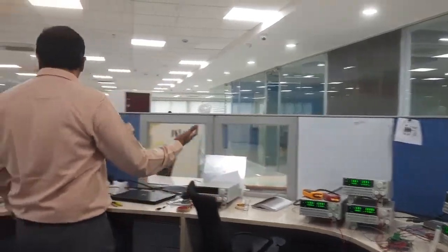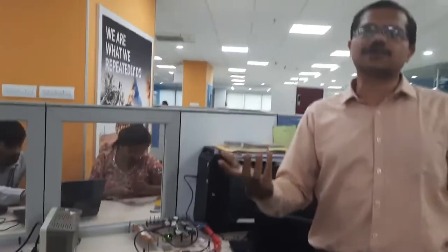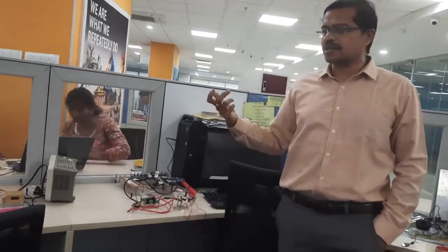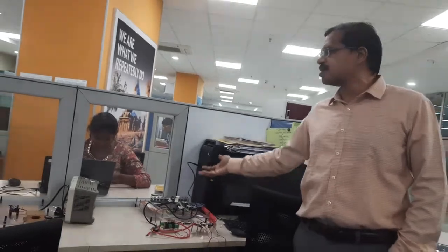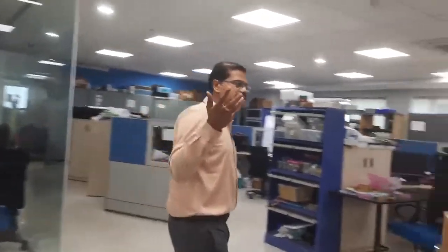After the power supplies, I am showing you some circuits related to level translators. When you are distributing from FPGAs to microcontrollers to i7, i3 computers and all, you require level translation to be done. Here the testing is going on for some of the level translator circuits. At Unistring we use these kinds of power supply systems and control circuitry, built sometimes with legacy MOSFET and BJT. Most of the time we use ASICs which already have the necessary 8-bit or 16-bit level translators inside.